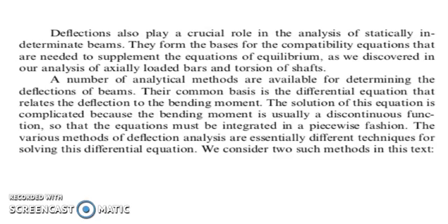Since there is a limitation for statically indeterminate beams in the use of equations of equilibrium, we make use of the concept of deflection. They form the basis for compatibility equations that are needed to supplement the equations of equilibrium, as we discovered in our analysis of axially loaded bars and torsion of shafts. So we make use of deflection equations so that we could solve statically indeterminate beams.